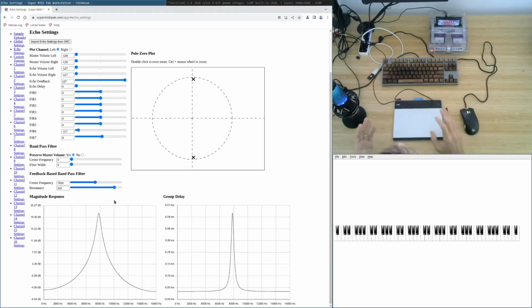you can see that as the noise is just on, the noise is harmonically rich, has frequency components all across the frequency spectrum. As I move the center frequency of the feedback-based bandpass filter, you can hear the specific frequency components being amplified. And so you can create a subtractive synth that way. And so I brought this up on the Discord, and some people brought up other ideas using the filter section of the SNES to also synthesize sound, which is pretty cool.